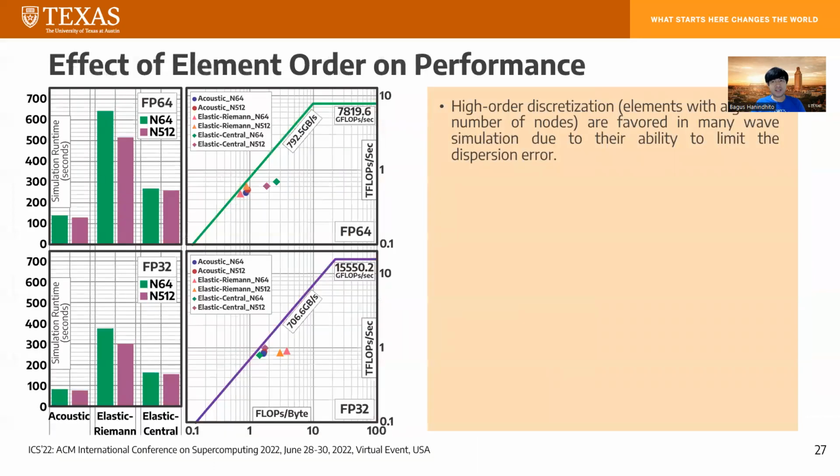And high order discretization, meaning that elements with a higher number of nodes are favored in many wave simulations due to their ability to limit dispersion error. So we would like to know whether we have an advantage from a hardware perspective if we use high order discretization.